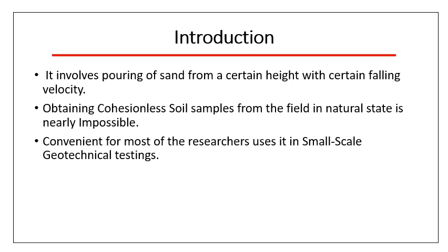So the next thing that comes to mind is why we have to use the sand pluviation technique. As you all know, because of the non-plastic behavior of cohesionless soil, which is sand, these samples are carried to the laboratory for certain testing, because testing in its natural state is impossible.